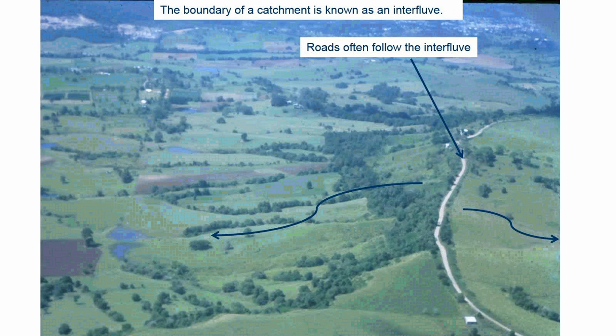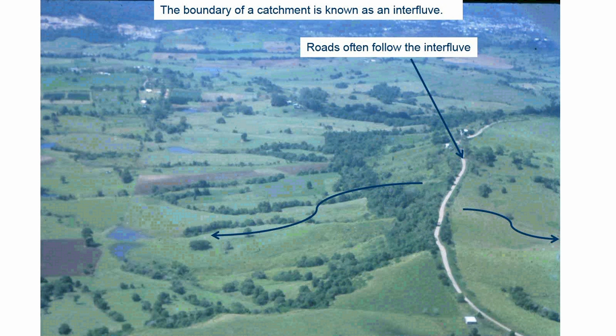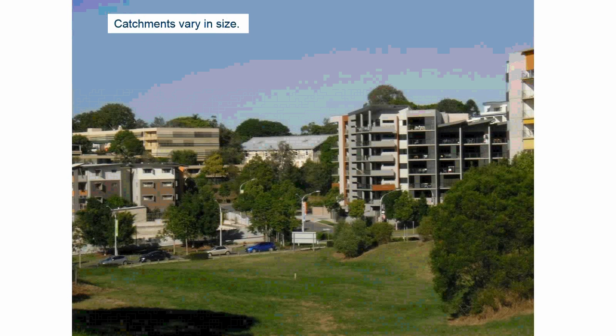Of course, the first part of hydrology is to understand our catchments. Again, this is taken from our previous slides showing a road along a ridge that is called the interfluve, and this is the principal component to start your hydrology assessment, understanding your topography.